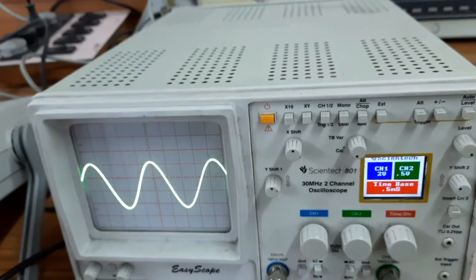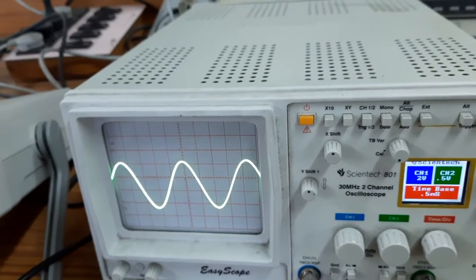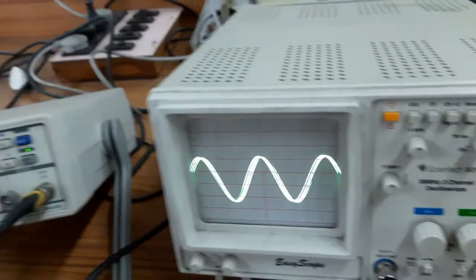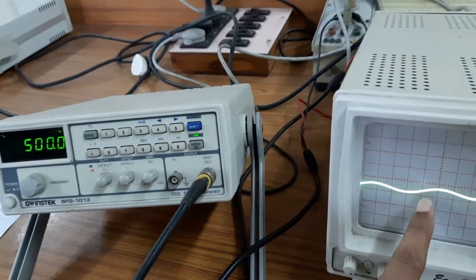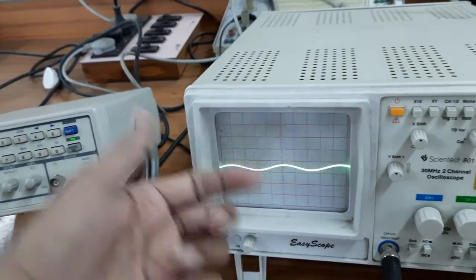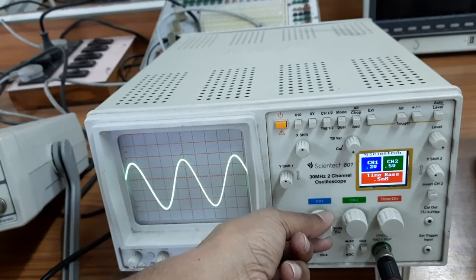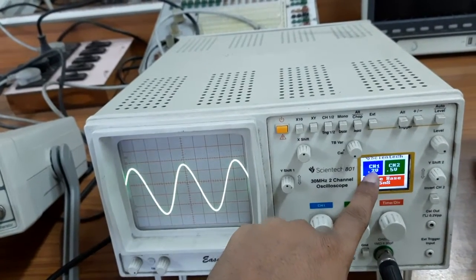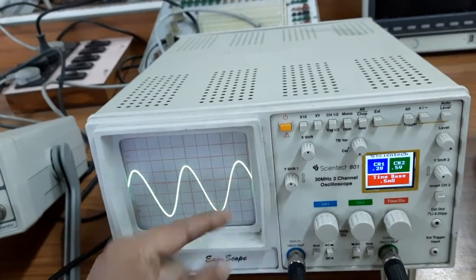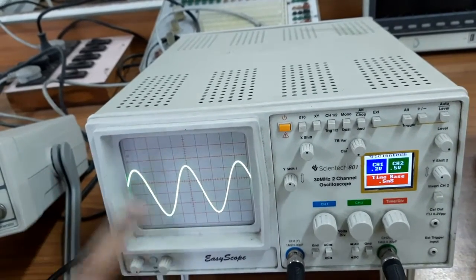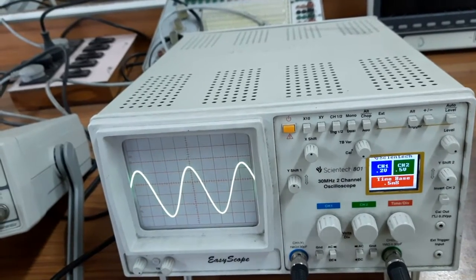If it is very low, how do we change our amplitude? Again from the function generator. The function generator says it is very low. So it is very difficult to measure now from the CRO. So what to do? We will change our volt per division knob to a lower scale. Say here it is 0.2 volt. It is 0.2 volt, and how much is it? It is 1, 2, 3, 4 point something. So 4 point something into 0.2 volt. In this way we can measure an amplitude.